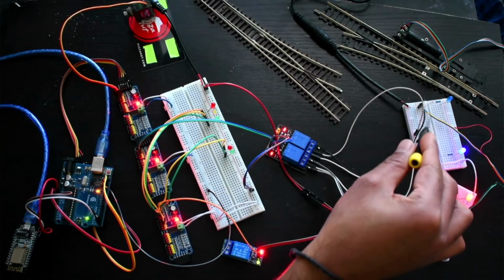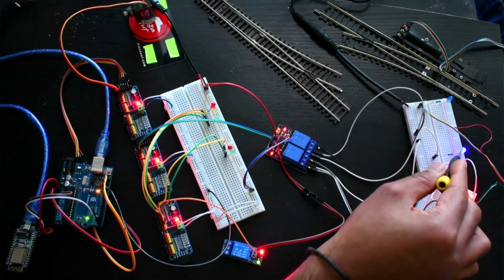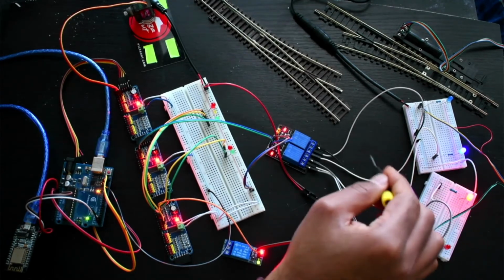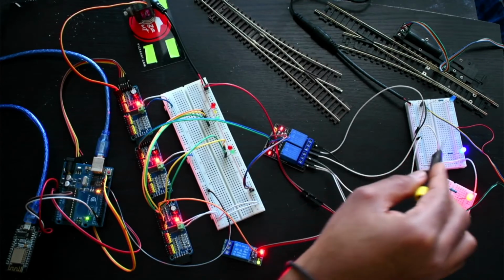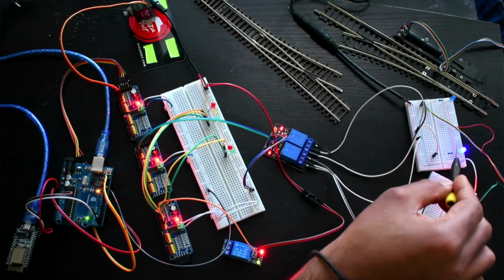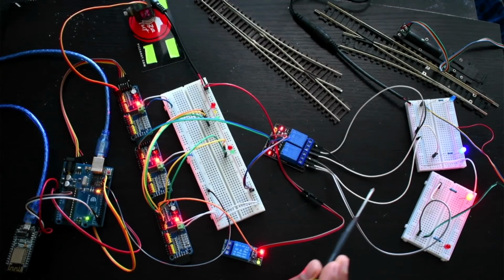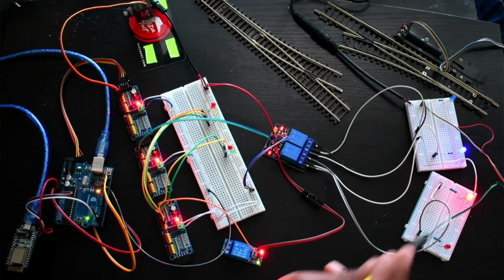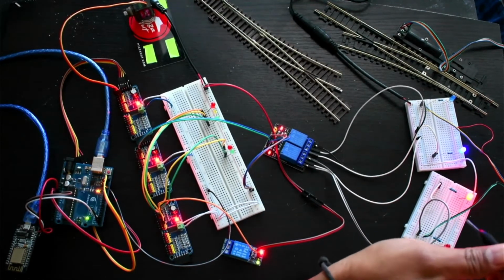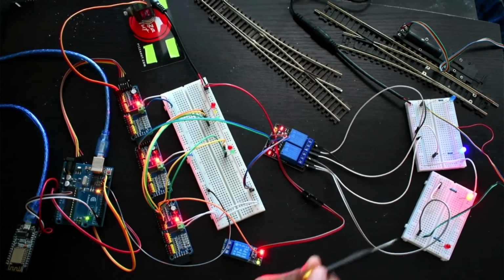If you see this black one and this white one, the one which is always glowing is the off state of the relay switch. Here, with this black and white, this white is always glowing. So never put your turnout wire into the one which is always glowing. Always use the opposite one, which is not glowing. And in the other one, you can see gray and white. Here the red one is always on, and this gray one is off. So never put your turnout wire into the one which is glowing, always put it into the opposite one.